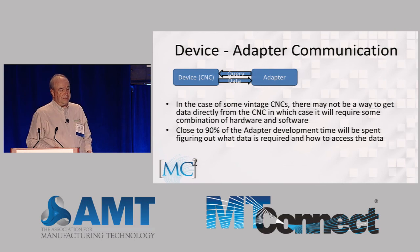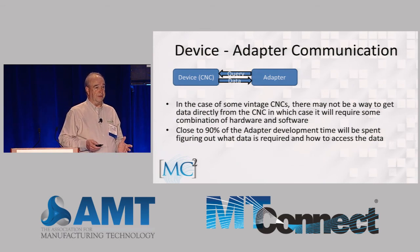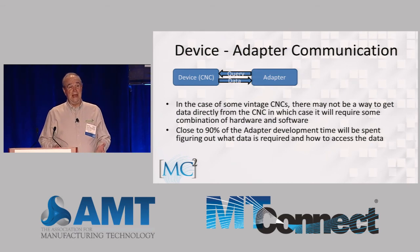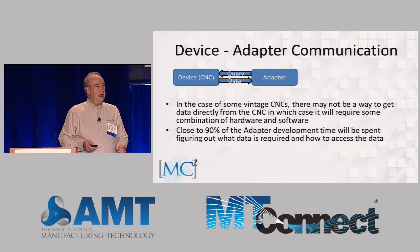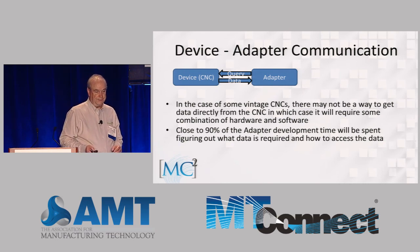In the case of some vintage CNCs, there may not be a way to actually get data directly from the control, and that's when you typically have to do some kind of combination of plugging into an I/O rack, or again, taking some simple data acquisition system to pick up some of the control signals and use that to actually extract information from the machine. What you're going to find when you're building an adapter is that you're probably going to spend the majority of your time up front looking at how you have to interface with the control, how to get the data that you want out of the control, and get that data sent up to the agent.